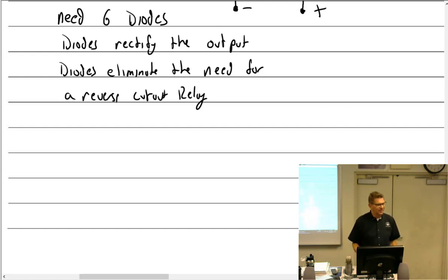So I turn on the machine, and I have a voltage. What does the voltage read when I just click on the master, and the generator's not running, the alternator's not running? Battery power. I'm reading battery voltage, which should be a little over 12. Exactly, 12.6.